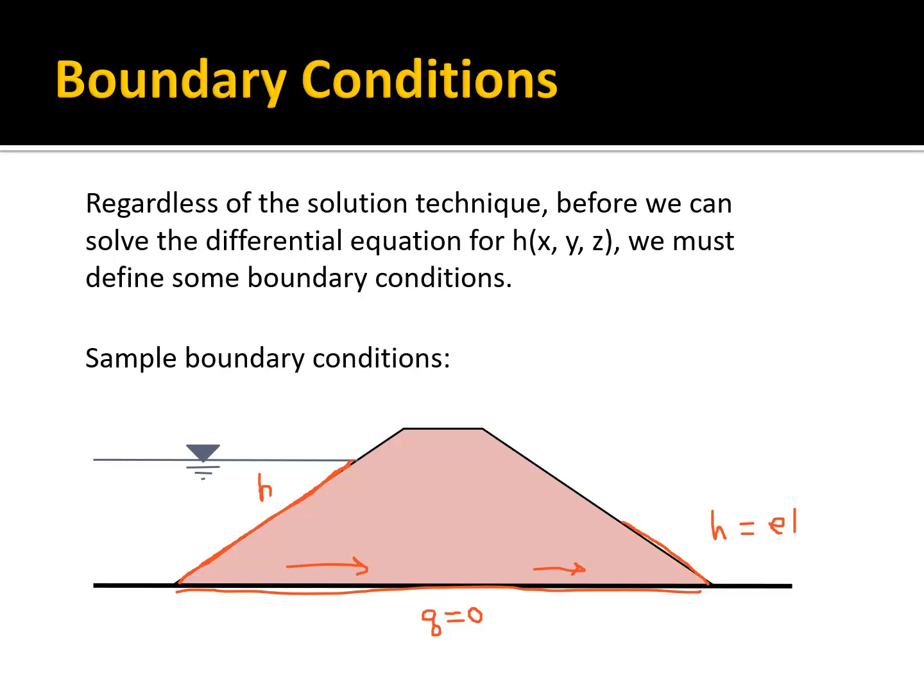And then ultimately we are going to solve for a phreatic surface, defining the upper limit of the saturated zone. And this is part of the solution here, so that's not really considered a boundary condition. Okay, so those are the classic boundary conditions we use in this case. Let me exit out of that.